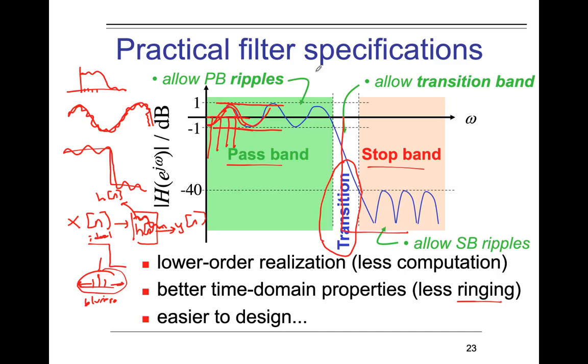Usually, as I said, FIR filters are represented with H of n, but for IIR filters, we don't use H of n. Instead, we use H of z, or H e to the j omega. Why? Because I cannot write a proper H of n equal to Dirac and this and that. It is infinitely long. Instead, I have H of z. It will have a numerator and a denominator, which will show us the relationship between input and output.